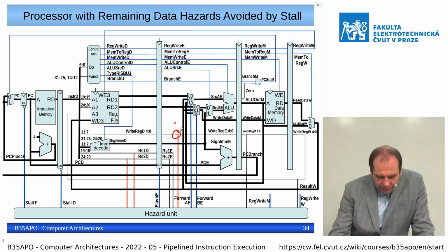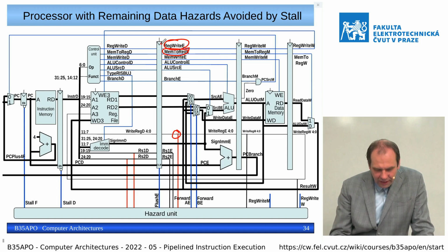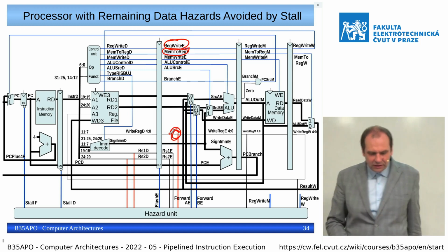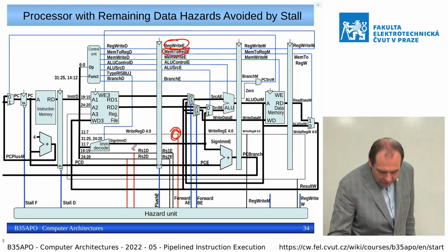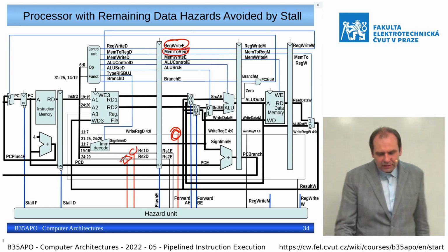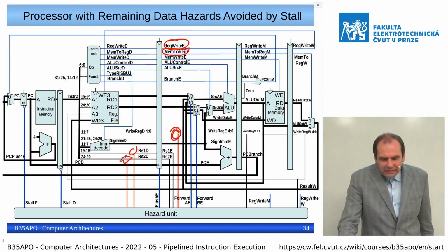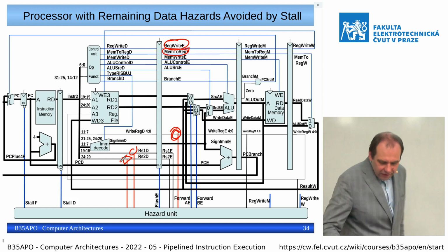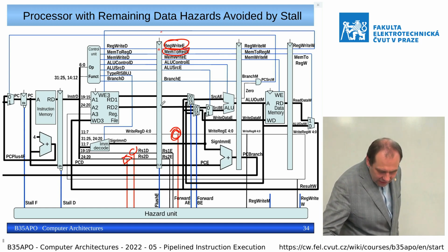So basically if we find that there is a write, mem to reg is active, there is a reg write E, and we want to write to this register which matches one of the decode registers in the decode stage, then in this specific case, we cannot allow full speed execution, and we need to clear this interstage register.